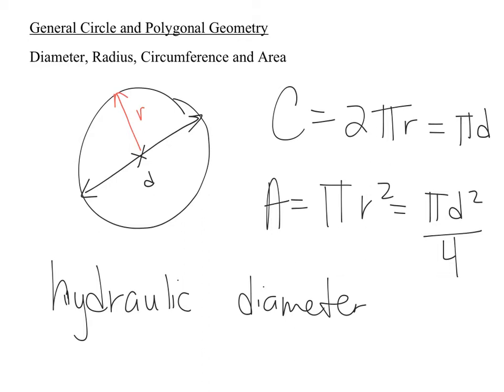You could have a square or rectangular HVAC system, like the heating ducts that go into the ceiling. They're usually rectangular cross-section, they're not circular. But when they're rectangular, what you give is called a hydraulic diameter. It's like the equivalent of diameter had it been a circle. So you can hear this term hydraulic diameter. It has to do with shapes that are not circular, but it's like a diameter.